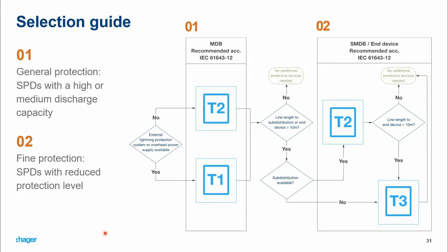For example, in your region in the Middle East, let's talk about an example which is commonly known to us, and let's see if we are able to come to a conclusion and select a type of device. Let's consider the very well-known Burj Khalifa. As we all know, it has an external lightning protection. That means they have external lightning rods installed on the building. So let's try to answer some of the questions in the flowchart and try to find the right kind of SPD.